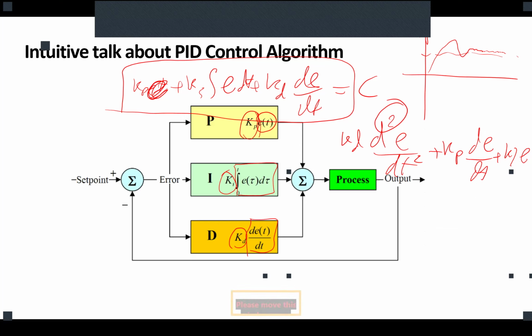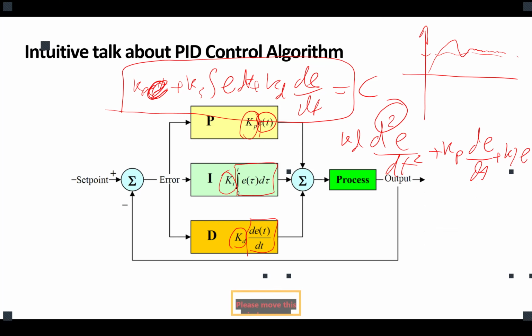How could we deal with that? Then the integral part kicks in. The intuition of the integral is basically summing up the value through time, or any axis that you want to define, any dimension. So what the integral does is calculate the accumulative error through time. If you have an offset, that I part would catch it and send a correction signal to eliminate it.